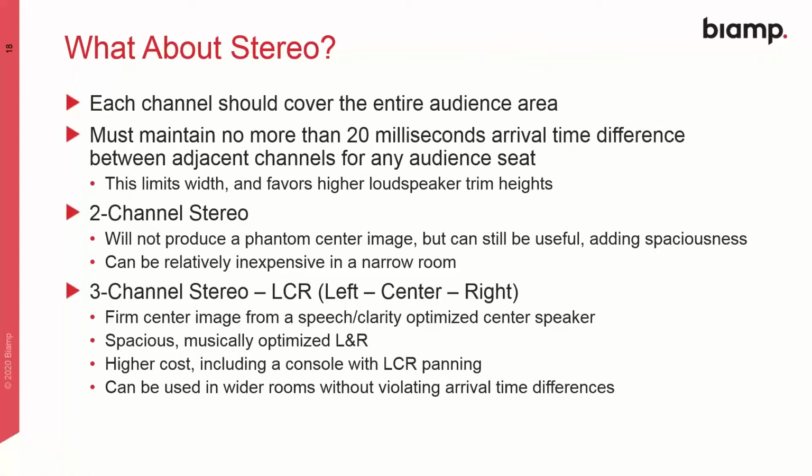What about stereo? You hear a lot of people say, well, you can't do stereo PA, it doesn't work like it does in the living room. Well, maybe yes and no. If you're doing stereo, each channel should cover the entire audience area. Left speaker has to cover the whole audience, right speaker has to cover the whole audience. That can be a little difficult.